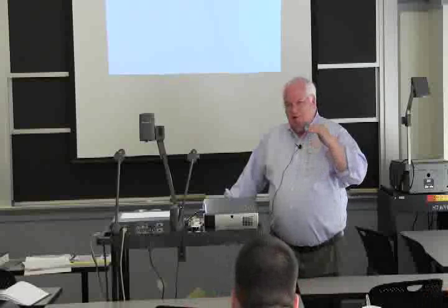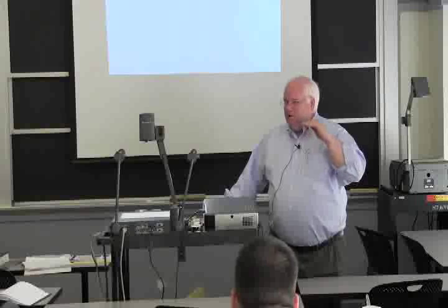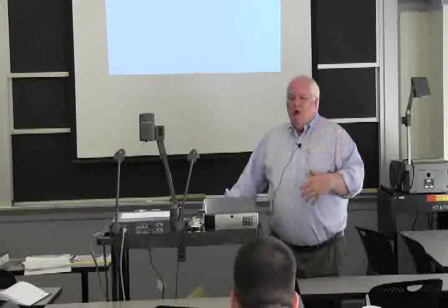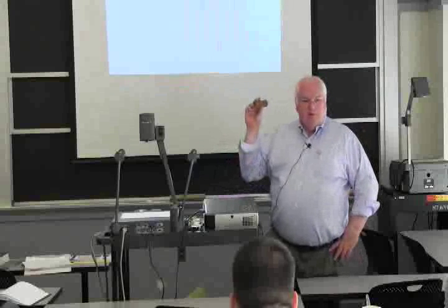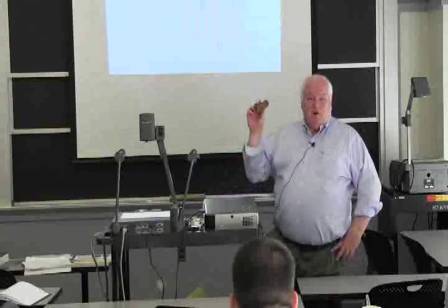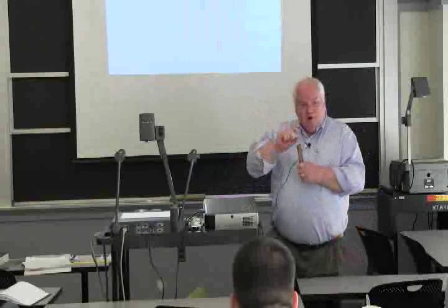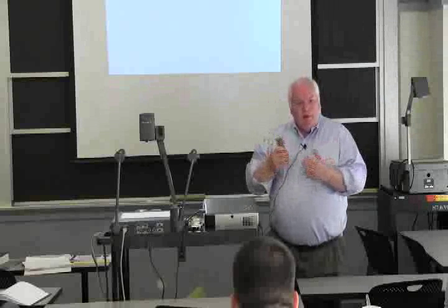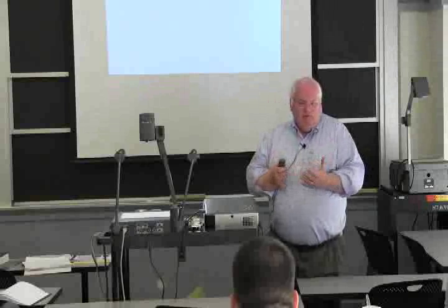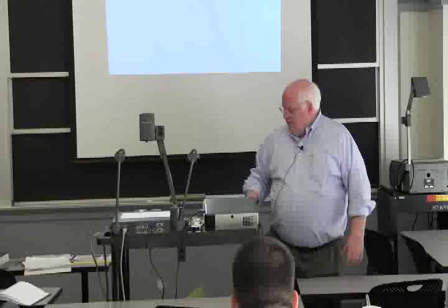Well, in the case of gold, you want to have as little scrap as possible, so it pays to have a continuous caster. Even though you may only cast something that's 12 feet long, it might be a bar like this of karat gold, and it may only be 6 feet long. But if you only have to cut off one little 2-inch hot top as opposed to 20 or 30, it paid for itself. Even though a little caster like that might be 5 or 10 million bucks,